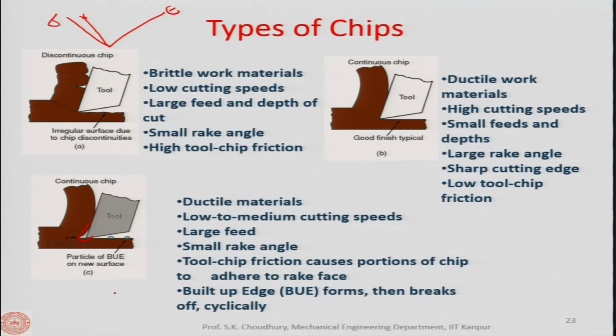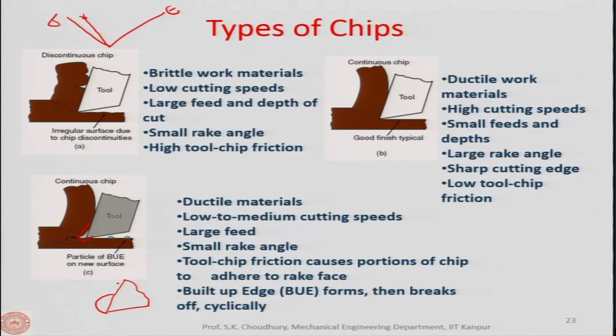And what happens is that it remains on the tool because of this reason. So let us say this is the tool, okay, and here I will exaggerate, this is the piled up built up edge, you can all see this, right. Now, the built up edge is a very hard material, because it is strain hardened material, because the chip is being strain hardened, because of the plastic deformation. So this is a strain hardened, very hard material, getting piled up in front of the tool. So when it breaks, what happens is, if we draw the curve of the stress along the rake face, the stress is maximum here, because at the tool tip the pressure is maximum, force is maximum.